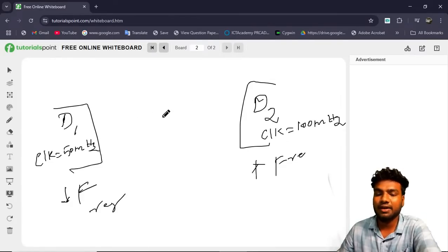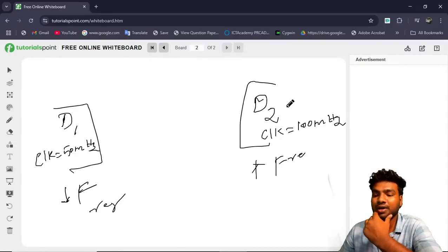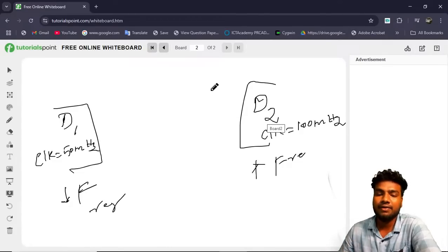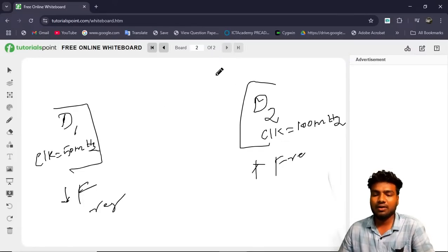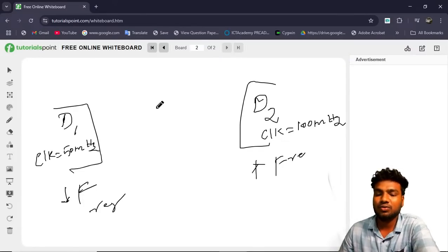For this condition we can't transmit data directly. If you transmit, there is a delay; device 2 will receive fast but device 1 will send slowly. So device 1 will send the data slowly, but device 2 will receive the data very fast. Device 1 is not capable of sending the data fast. So there is a chance of an error or unknown state, some conflict in the data, so an uncertainty will happen. For this condition we can use a FIFO memory to make proper data transfer.